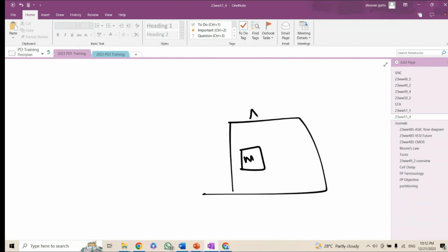This is the local logic, and this is the adder. Maybe you need to use a subtractor which the foundry guys don't have as a macro. Then what will you do? The subtractor logic will sit here and communicate like this, and you need to meet the timing for this. If they have this logic also, then you will be given it as a macro like this. Then if these two macros communicate, what will you do?